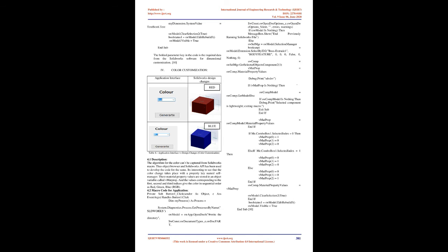3.1 Description. The algorithm for the dimensions can be directly captured from the SolidWorks macro feature. Thus, the algorithm for one edge of the cube is captured at first. It requires the corresponding key for each side's dimensions, which is assigned by SolidWorks in sequential manner. In figure 4.1, Dimension tab, the marked region is the key for the dimension of one side. Likewise, following dimensions are used in the algorithm, thereby developing a suitable customized dimensional design.